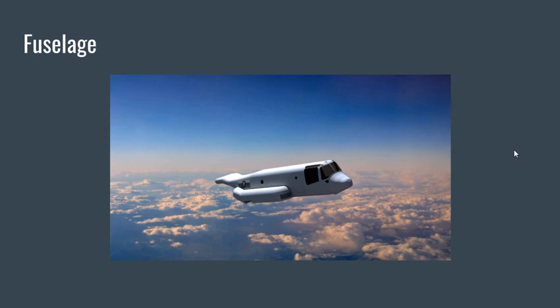Alright, for the fuselage assembly, I used Sketch Tracer. So I imported a JPEG into Sketch Tracer and then modified it to be the length of the actual aircraft that was found online. So I used a lot of generative shape design. In there I used the multi-section tool a lot for the cockpit, the nose cone, and the main fuselage and doors. Also, I used split and extract tools to do the windows and some of the back window as well.